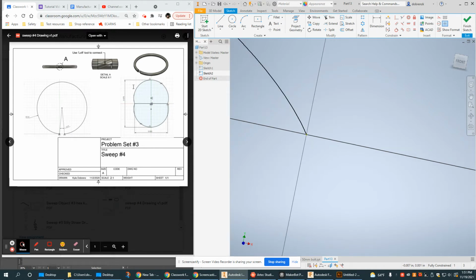All right, so what do I have here? I've got two arcs, two kind of chubby little arcs. After I create the arcs, I'm going to use some construction lines. I've found that construction lines can be used to do lots of things and make things very, very simple that would otherwise be complex or create a need for lots of dimensions.